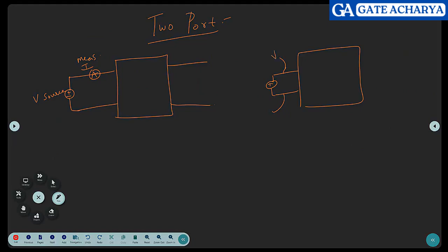Right? There are two ways to do it. Now, which one is preferred depends on the situation. I'll give you a case where a voltage source is dangerous. If the input impedance is 0.01 milliohms and you give 1 volt, how much current will go? 1 divided by 0.01 milliohms, which is 10 power minus 5. So 1 lakh amps will go. In other words, you are spoiling your voltage source.